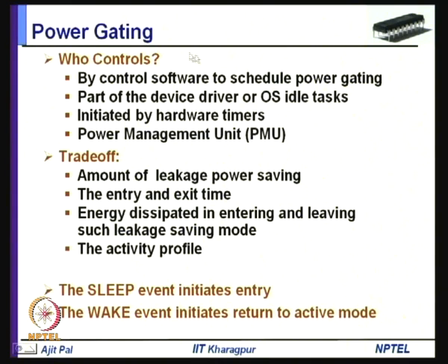Then whenever you do power gating, there are several trade-offs. The trade-offs are how much leakage power saving you can do by doing power gating, and the entry and exit time. As I told, the entry to the power gated mode will take some finite time. So, there is a trade-off between how quickly it can be done and how much power saving can be achieved. Then the energy dissipated in entering and